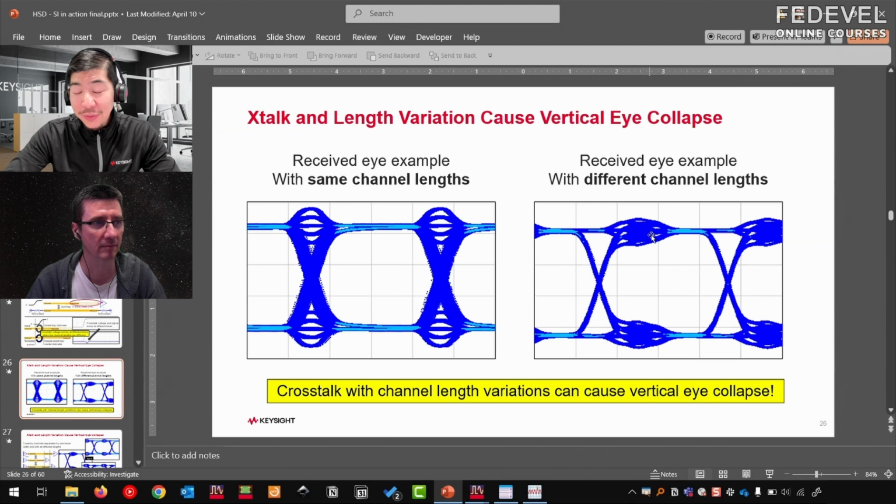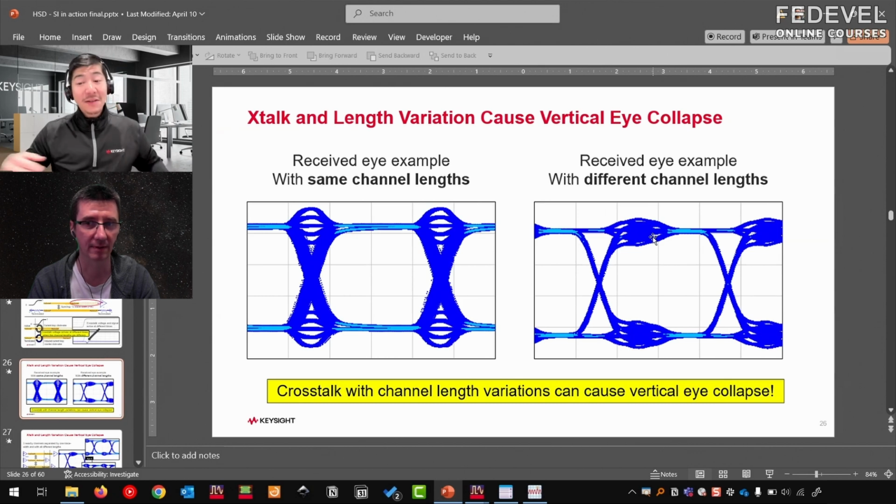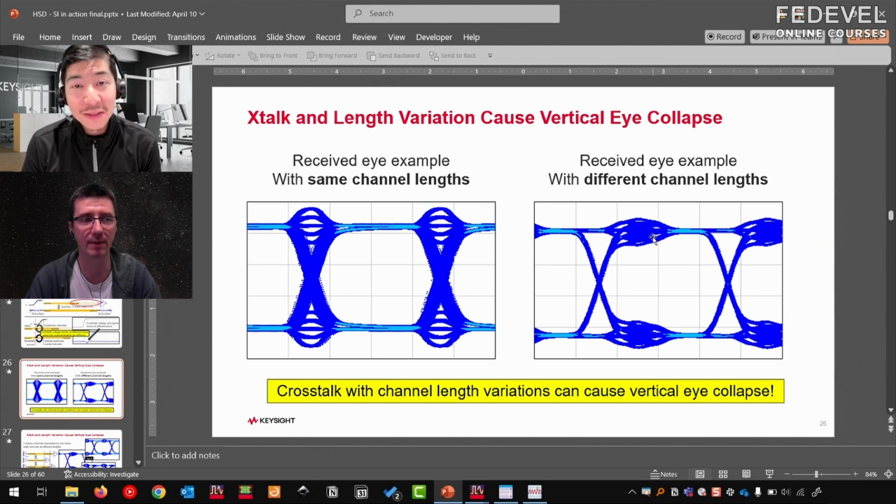You can mess with your designer friends, SI engineering friends. Oh, I understand now. I understand. Because when they are exactly the same length, the crosstalk is always happening where the edge is aligned. Yes, that's correct. That's why we see it at the moment where the edge is.